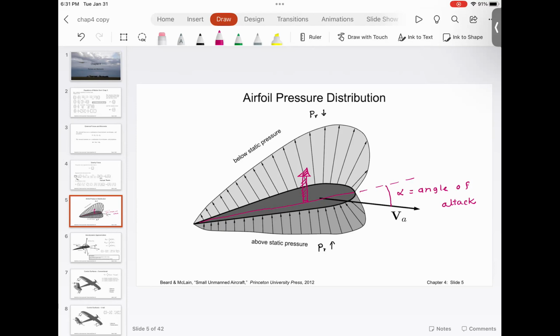You don't want to go beyond the critical angle of attack, because that is when flow separation occurs, which means the flow is no longer attached to the airfoil. Now, there are two ways this can be used. If you look at very highly maneuverable aircraft like the F-16 and its variants, they deliberately disrupt the boundary layer so that there is selective drag on certain parts of the wing. And the reason for that is it makes the aircraft extremely agile.